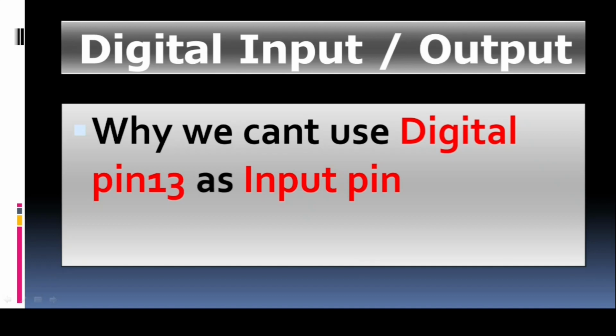We can also use an analog pin as a digital input and output pin. Just write the name like A0, A1, etc. Whichever pin we want to use, we can use.